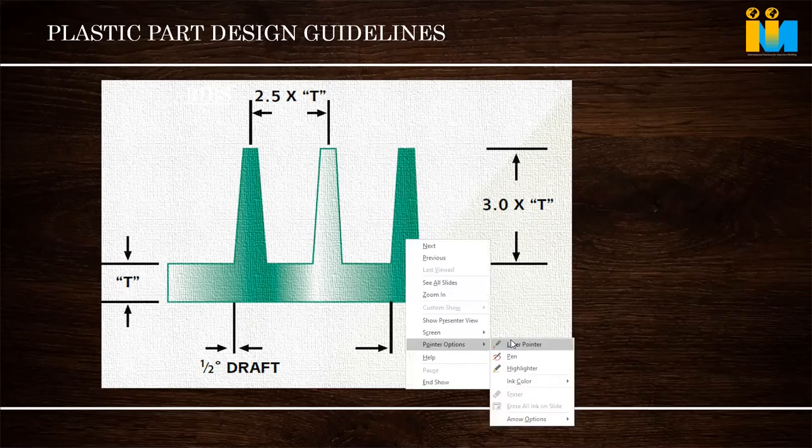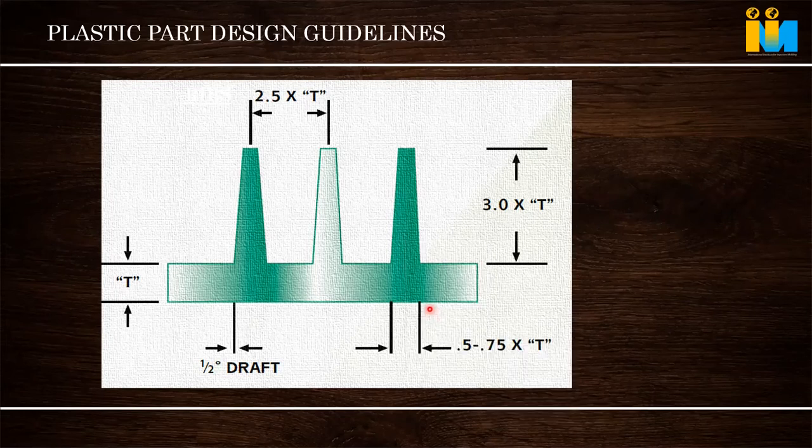We have seen the notch impact strength of the polymer in the data sheet. Sharp corners tend to form notches. The unnotched and notched impact strength we have seen: unnotched was 3,500 and notched was just 600. That shows the difference in performance. So don't give a chance for a notch to form. Notches form in sharp corners everywhere, so don't make sharp corners, especially where function or loading is coming.